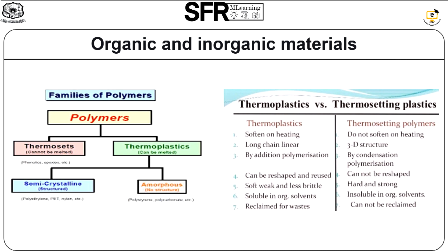These materials are ideal for moulding and casting into components. They have good corrosion resistance. So, excellent resistance to corrosion, ease of fabrication into desired shape and size, light weight, strength and rigidity have established these polymeric materials, and these materials are fast replacing many metallic components. PVC, polyvinyl chloride and polycarbonate polymers are widely used for roofing and cladding of buildings.